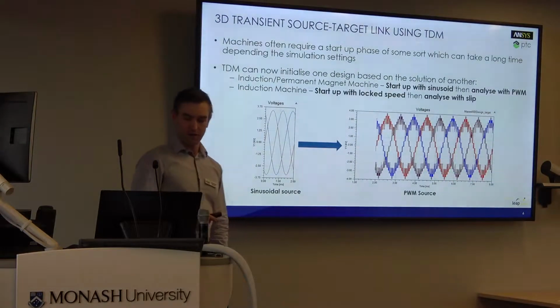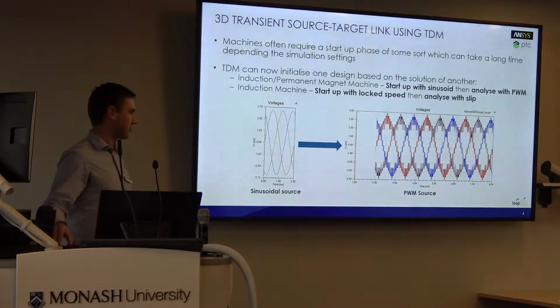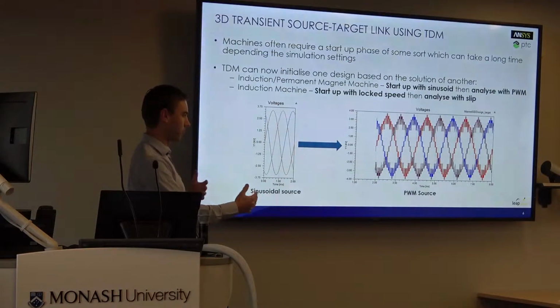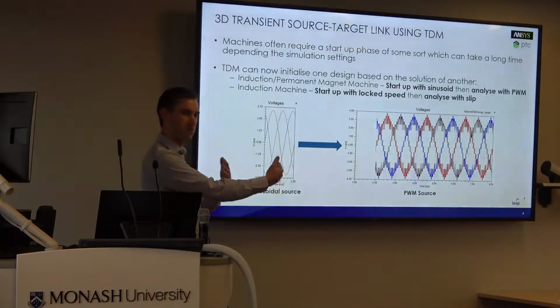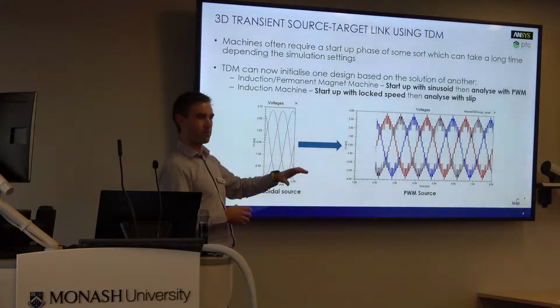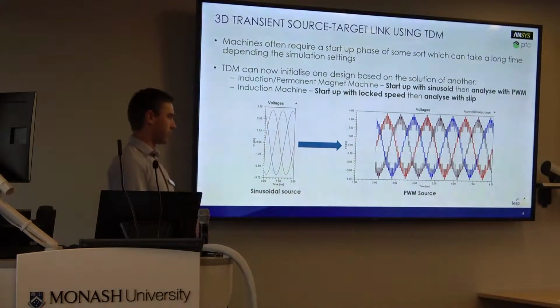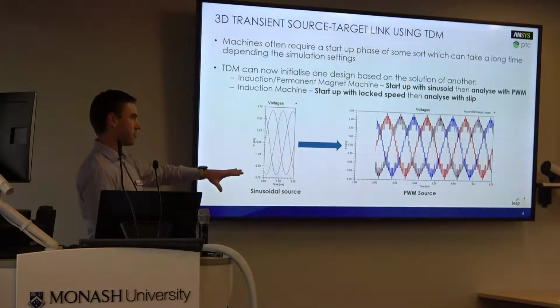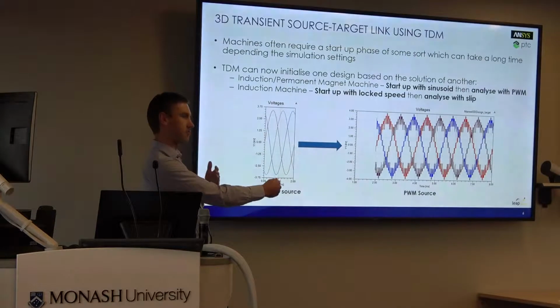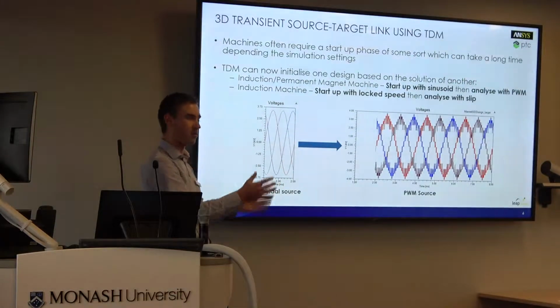For a lot of very complicated 3D solves, we find there is a startup region to the motor workflow, and then there's another part where we want to actually do some serious analysis. An example of this is when we want to look at exciting induction machines with PWM cycles. Usually if you want to use pulse width modulation with an induction machine, you've got to wait a very long time for the machine to settle down before you can start getting good data out of it.